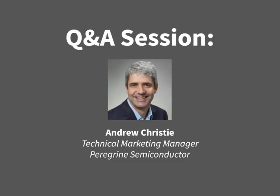Thank you. Okay, on a connected note, can you explain why the 28 gigahertz phase mapping and/or calibration is important? Okay, so I think this links up to one of the questions from earlier regarding the 19601. Typically you may see an interaction between the phase shifter and the attenuator. So when one is changed, it creates a small change in the other. What we're showing with that diagram is that when you use the correct mapping, which is what that series of plots is showing, you can remove that interaction. And because our parts are so consistent, we can provide a mapping that will, as you could see from the error, which was very small, less than plus or minus 3 degrees, achieve a very tight phase and attenuation control over the whole range of both.